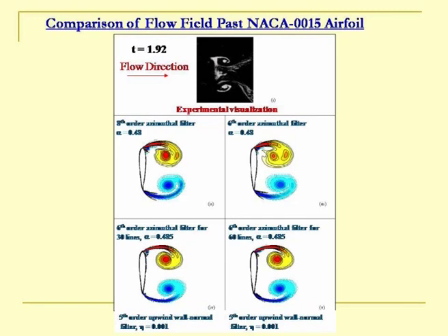In fact, those of you who do not belong to aerospace engineering may have wondered why the wing shape is like this. It is for this, that if you have a sharp trailing edge, you can actually force the flow to change locally there, whereas if you have a rounded edge, then the effects are diffused and it can actually cause a lot of unsteadiness, whereas this kind of sharp change in the trailing edge actually helps in a better performance of the wing, and that is why this is shaped like this.